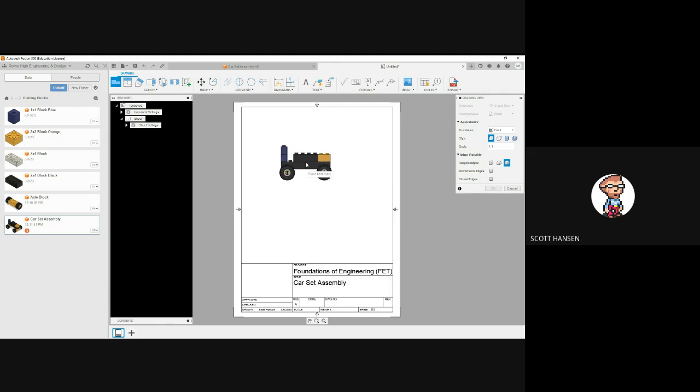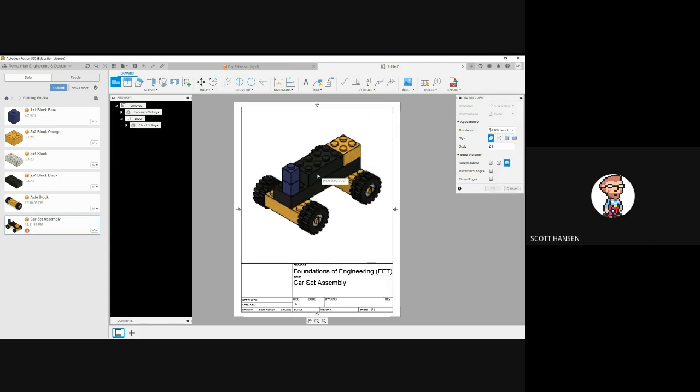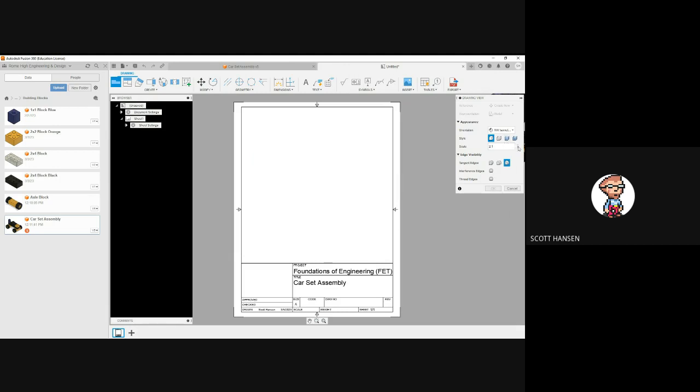And so this first view is going to be in an assembly view. Typically for the assembly view, I like looking at the isometric view of this thing. Makes it a little more clear to see what's going on. Let me change the scale here. Let's see if 2:1's too big. That's too big. Let's see.